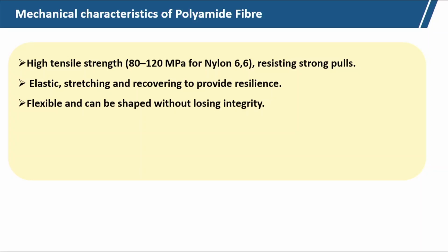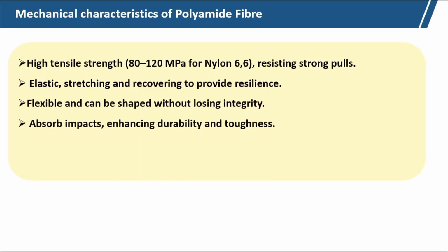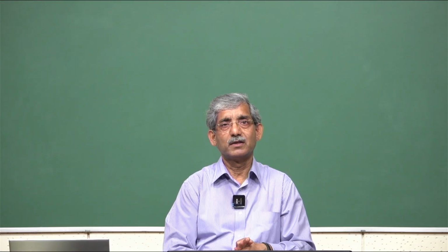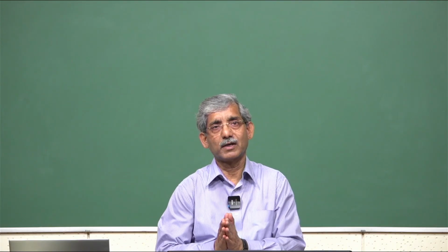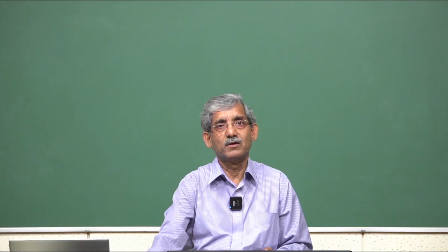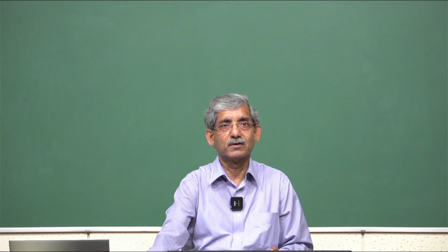So, these fibers are flexible in nature, absorb impact, and enhance durability and toughness. So, basically the work of rupture of nylon is very good. That is why for different applications where impact absorption is important, we can use nylon fiber, nylon 6 or nylon 66, which enhances the toughness.